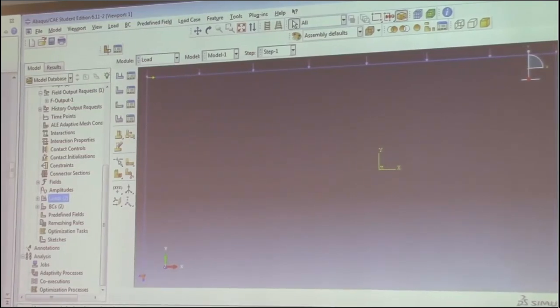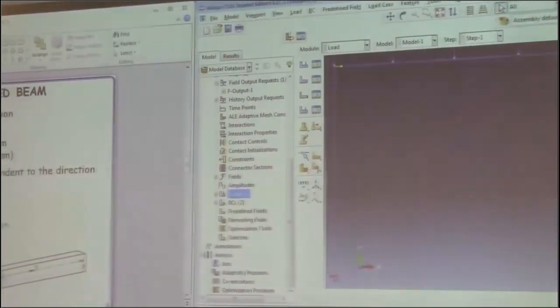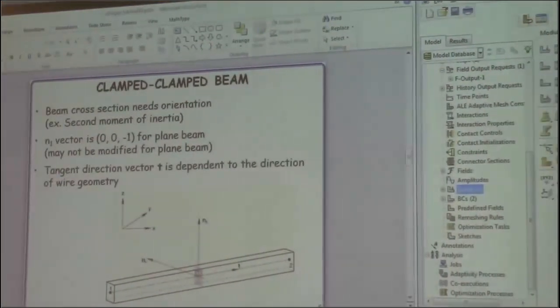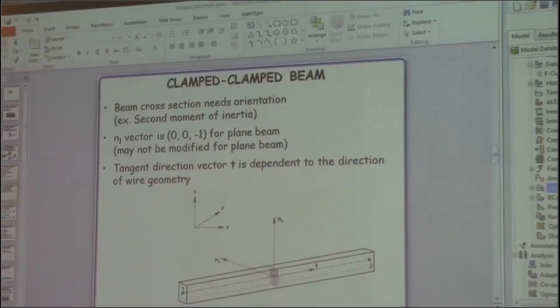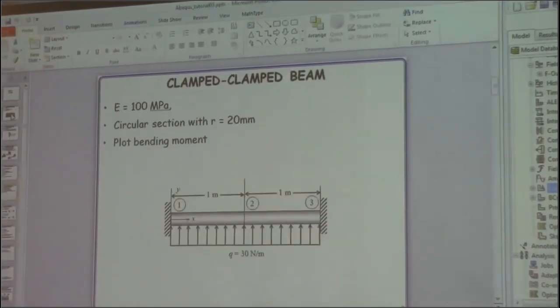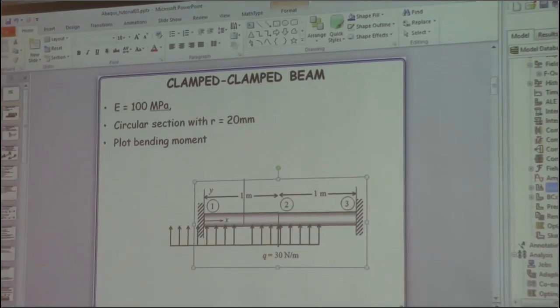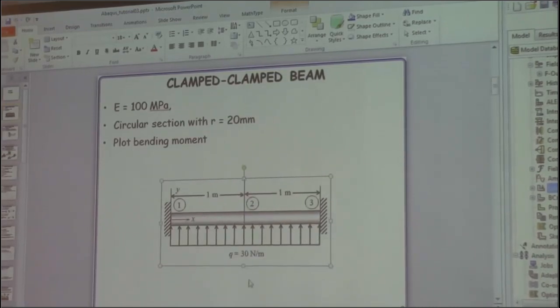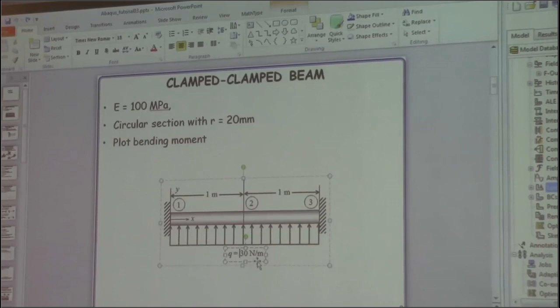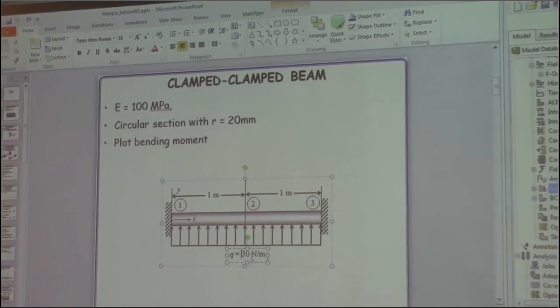And be careful when you try to do the example on the slide. It is a little bit different. So you can see here, it is also a distributed force, but this distributed force is given as a... Oh, sorry. What's the difference here? Per length instead of per unit area? Yeah, so the unit is different. This is a line force.